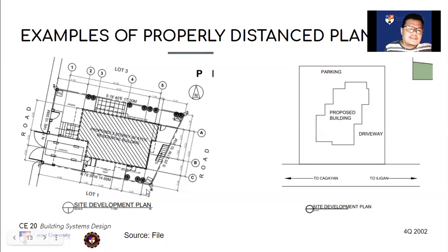But on the rear side, you can squeeze it to 1 meter only if the land is not flat. But in the front stage, you will notice that it's using 4 meters. This is a major requirement in some subdivisions. It should be 4 meters. But if you own the lot, you can actually use 2.5. Okay. But that 2.5 meters should not be near a bedroom. Okay. In this plan, they actually utilize the frontage for living rooms. That includes the first floor and the second floor. All are living rooms. And bedrooms are located in the middle. So that's allowed.